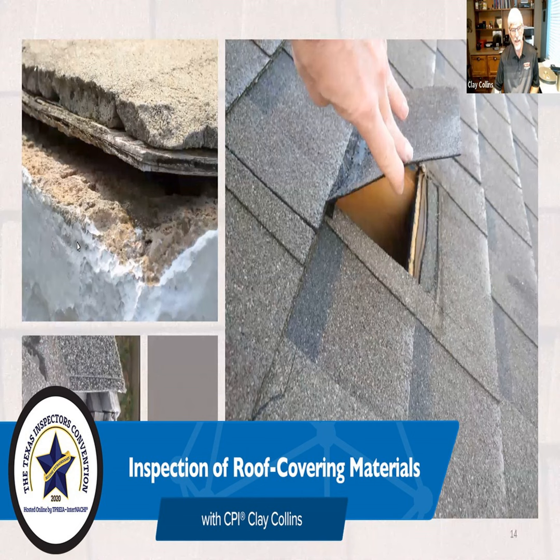Rain. A low slope roof is going to have that rain hit at a straight down or closer to straight, and the impact of it is going to be more than if it is at an angle. Hail. We'll talk about hail towards the end of this, but obviously hail is going to be damaging to a roof. Sunlight, UV rays. Well, that shingle is intended to protect everything else and is designed to handle all the UV rays that might be there.